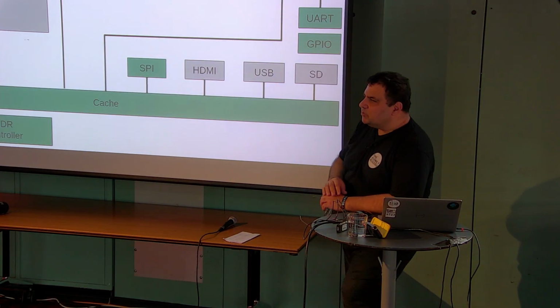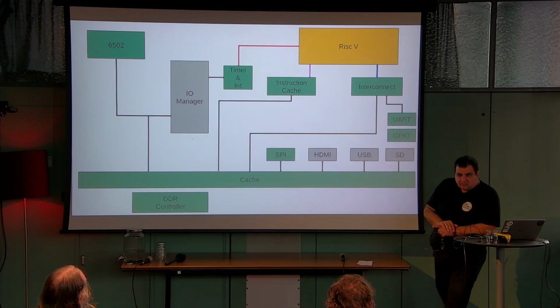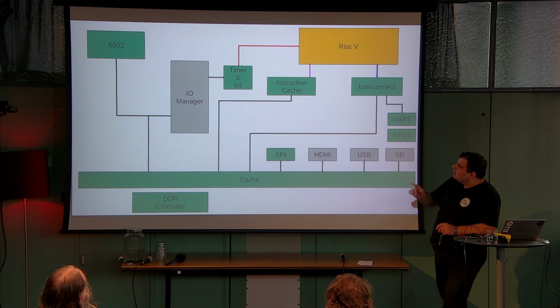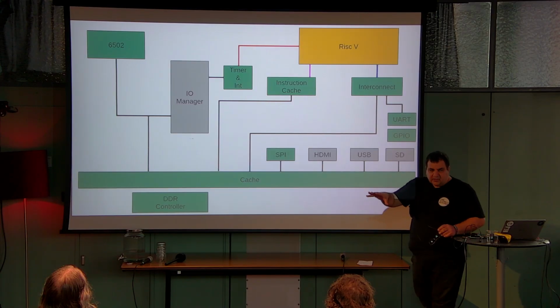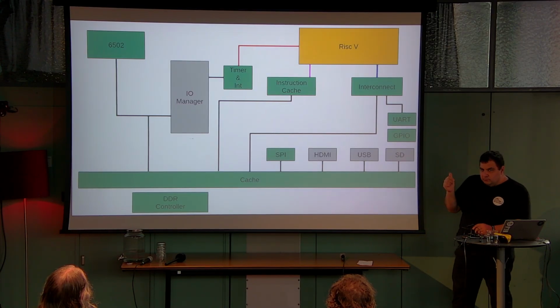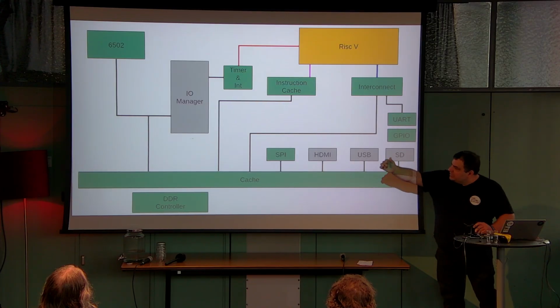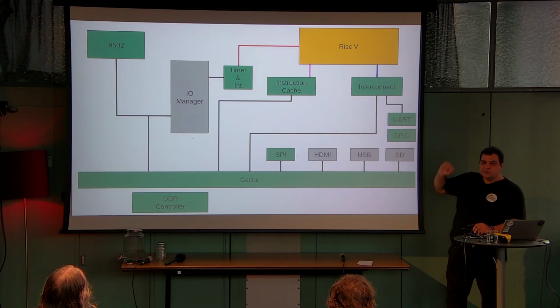So instead, what I'm doing is this. All of the right side is a 32-bit machine. It's running some operating system that I wrote for it. And the idea is, as long as the 8-bit is just executing code, it's executing code. Whenever the 8-bit is doing I/O, it interfaces into the 32-bit side, and it interrupts the RISC.